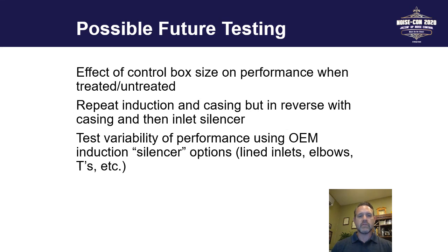And then also look at the test variability of performance using OEM induction silencer options, things like lined inlets, lined plenums, elbows, T's, those types of things that are very traditionally used.